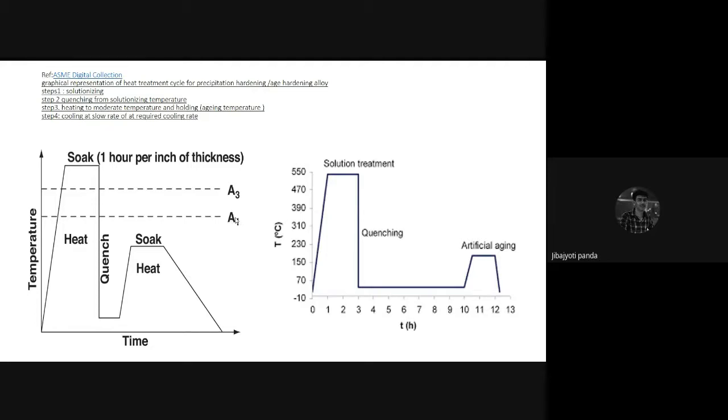That is actually called the lower critical temperature. Remember, in heat treatment we use these terms: lower critical temperature, A1, or sometimes AE1. Do you remember what E represents? You can write A1 or AE1. AE represents equilibrium. Similarly, you can write AE3. So if A1 is the lower critical temperature, what is this then? A3, the upper critical temperature. Very good.